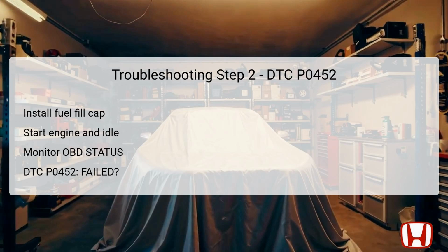Return to inspecting the connections at the FTP sensor and the ECM to rule out any loose connections or faulty wiring. If the HDS indicates not completed, continue idling until sufficient data is retrieved.